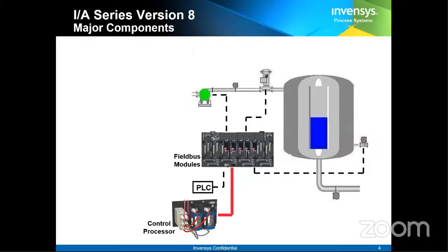Now, one more very important factor is that if you use an integral action, it will take a lot of time to bring the error close to the set point. We do not have that much time, right? Let us say you want to maintain a temperature inside a boiler or in a tank, you cannot wait for 1 hour, 2 hours, right? You need to bring it to the set point as early as possible. So integral action will have a very long response time.